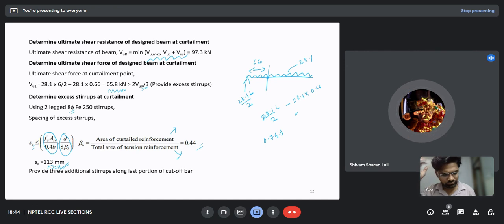For one-way slab, I had studied that this provision is applicable, but for the two-way slab, where there are restraint conditions, 50% should be at the top. You are talking about the cranking part, for the restrained slabs. 50% should be above and 50% below. That cranking is being provided. We bend 50% so that it takes care of the negative reinforcement at the support, and 50% we continue to the support only.